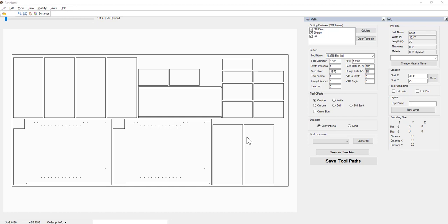Well, we're going to take a look at cutting order. Cutting order is a method that will allow you to help hold smaller parts and be able to cut smaller parts with limited vacuum. You want to think about the way you cut, what parts get cut first, and also where the plunge point of that router bit is going to start cutting.